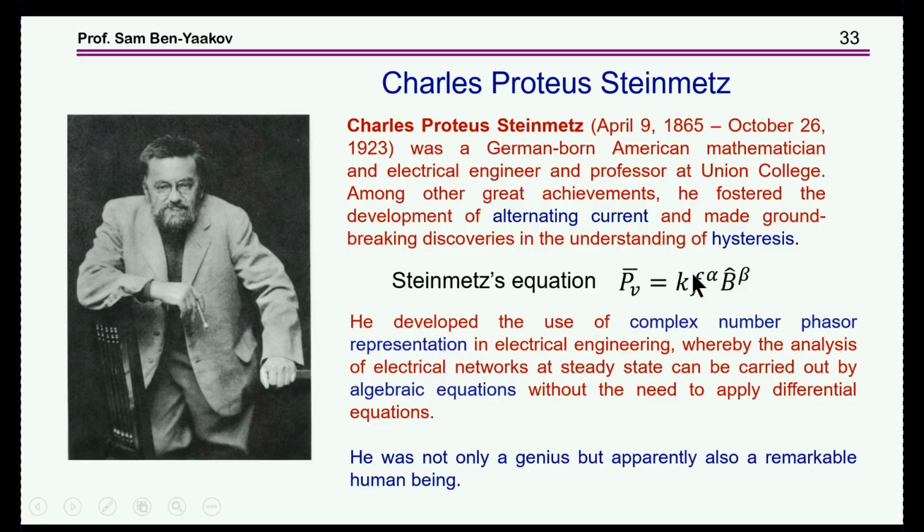That is when we write j omega and do algebraic manipulation. This is Steinmetz's work. So he was really interesting. And one of the things he worked on is ferromagnetic material. As you might know, there's the Steinmetz equation, which describes the losses of a ferromagnetic material as a function of frequency and excitation, the B magnetic flux density.